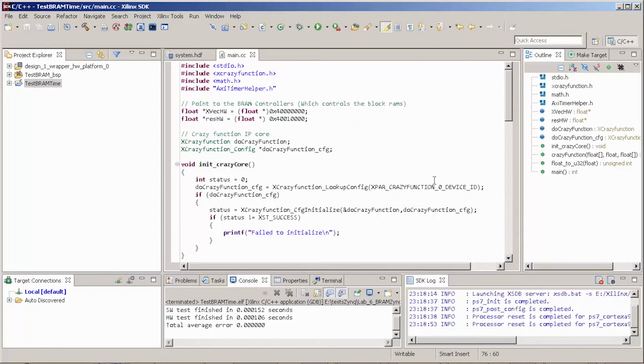Okay, guys. So this is the Zynq SDK. I already have a project that is going to run this IP core to test. So basically, we have a header that is going to point to our generated driver from the Vivado HLS. Detail: this driver is just created for AXI-Lite interfaces. AXI masters, I'm not sure, but for sure AXI stream or BRAM IPs alone, no.